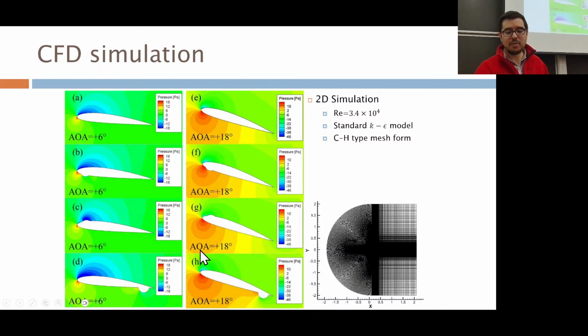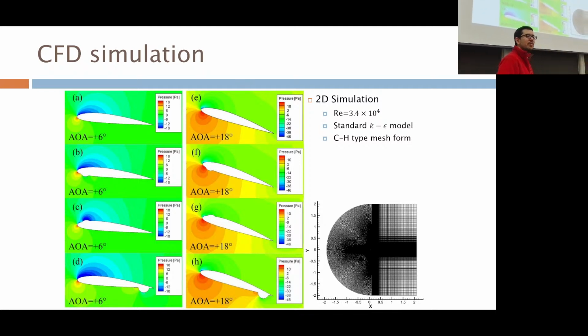And you know, what was tricky though is that he had to actually change the geometry, okay, of the airfoils. So we determined that this design with the pseudo flap, that does something. What about these other designs? What about putting a bump on the top, front portion? Does that do anything positive? You know, I think Michael, you suggested that you could try to increase the thickness of the foil a little bit, right?